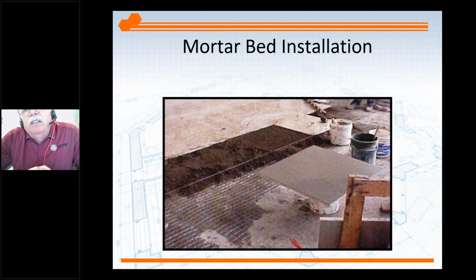Double the cost of the installation over thin set, and probably going to double the time. This is going to give you a very flat level floor. You can generally use very tight joints for these natural stones or tiles. And these are the type of installations where you can slide the quarters across, because they're going to tap that tile or stone into the wet mortar bed.